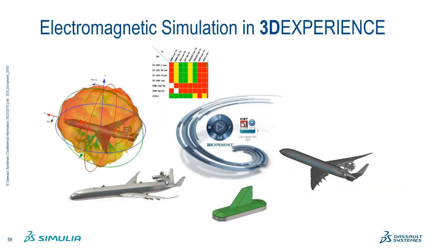So putting all this together, we've seen that our solutions for communication system design include tight integration between CAD, CATIA, and CST simulation to ensure digital continuity, rapid and easy antenna prototyping using Antenna Magus and the array tools, easy integration of antennas onto aircraft geometry using assembly modeling and anchoring, parameterization and powerful design of experiments for antenna placement analysis, tracking of antenna key performance indicators such as radiation pattern and power delivery, and an interference workflow which enables the antenna coupling to be combined with radio system models for co-site interference analysis.